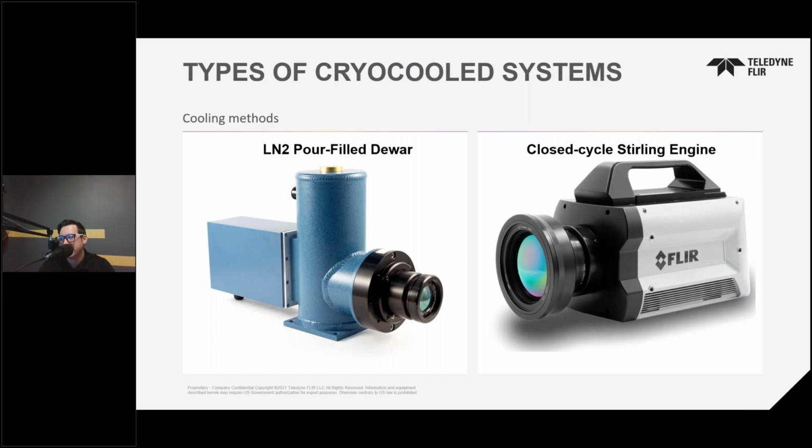The only gotcha here is that in infrared, we can't typically add more light to get our target or scene to improve a capture that requires a short exposure time. It just doesn't work that way. Whereas with visible camera systems, you can add a lot more lighting and decrease your exposure time and get some great image captures. For us, we're dealing with the target's own energy. So your target's energy typically dictates how fast you're going to be able to run a camera, which kind of leads into the speed topic there, so I'm not going to follow that too hard.